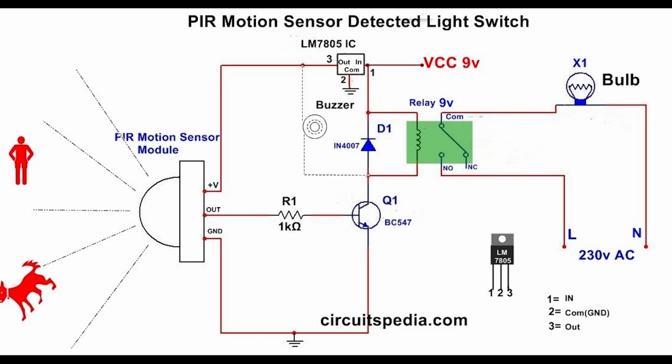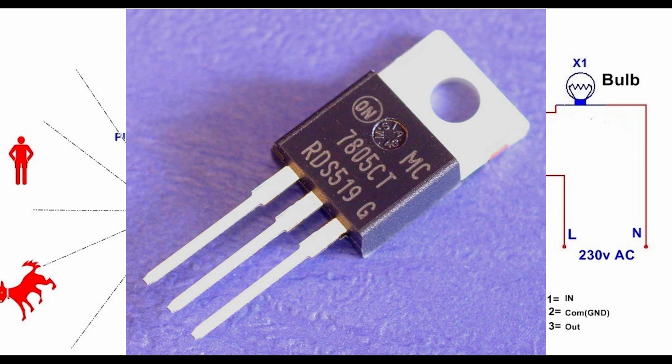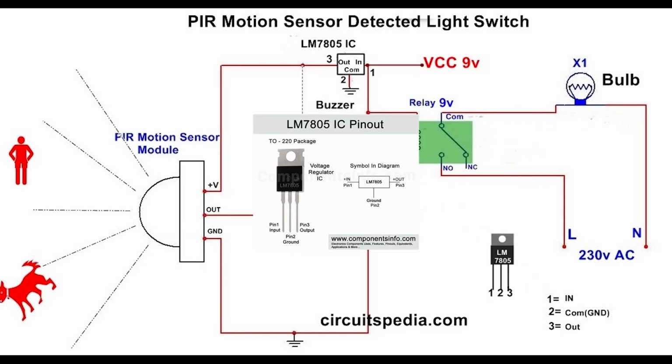This is a very common IC in low ampere and low voltage regulation, but it generates a lot of heat. So that is a very simple design. You can easily regulate some common voltages using this LM78 series, sometimes 5 volts, 6.2 and 8.2, 9 volts and 12 volts, 15 volts, many ranges of voltages.